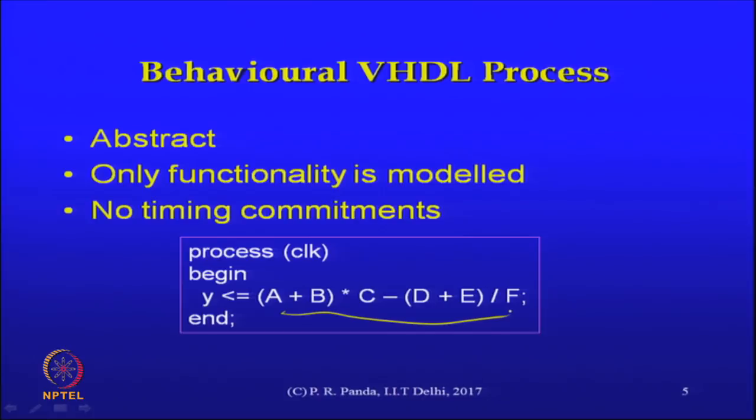Just like there is a value to zero delay assignments, there is a value to these kinds of processes where a complex functionality is specified and we just have a sensitivity to a clock. No timing commitments means that we are not really saying when the addition should happen, when the multiplication should happen, when the division should happen and so on. That should be the output of the behavioral synthesis process.